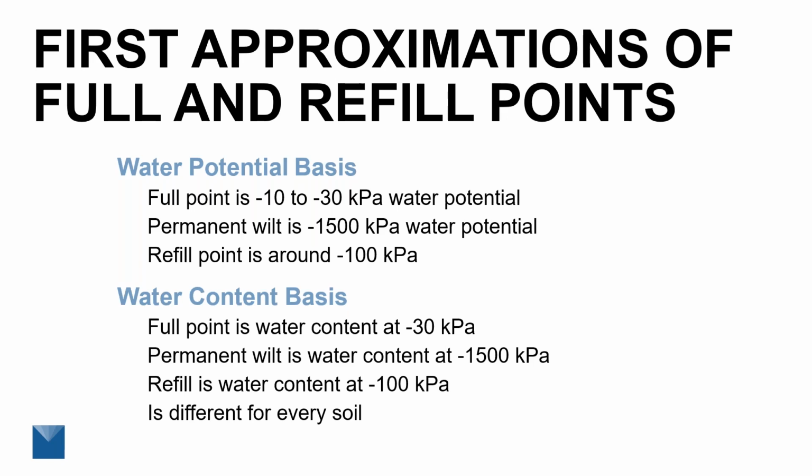Now, one thing to remember is that these probes in the field measure volumetric water content. Quite often, the laboratory measurements that give the permanent wilting point and field capacity are gravimetric water content, so need to be multiplied by the bulk density.